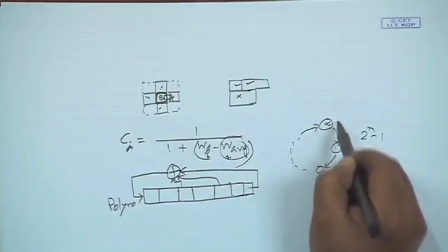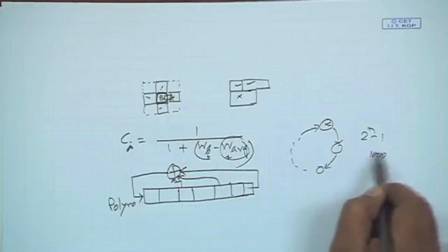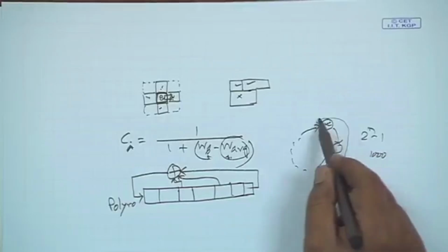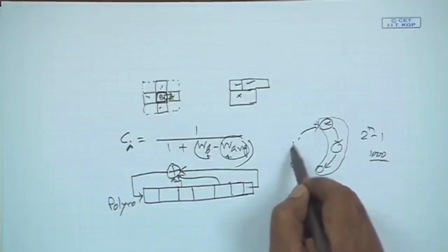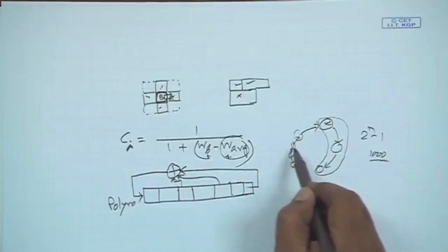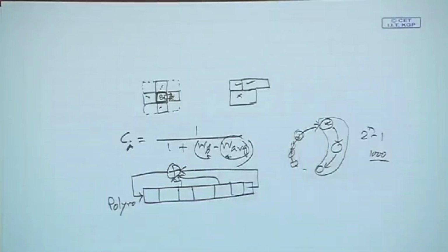If you start here and run for 1000 cycles, you will get some set of patterns. If you start at this point and run for 1000 cycles, you will get this other set of patterns. So depending upon the seed value, the sequence generated will vary. As a result, the fault coverage, power consumption, temperature, everything will change. So, that is another parameter.